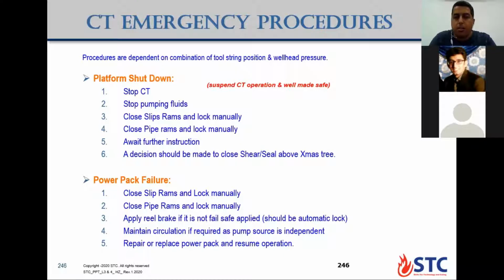It is the same onshore, if you have a siren or alarm for drills like H2S or any drills on the rig site, you will make the same steps. You will shut in, stop coiled tubing, stop pumping, go to the bottom, then close the slip and pipe ram, wait for instruction and go to the master point. This is the same situation.